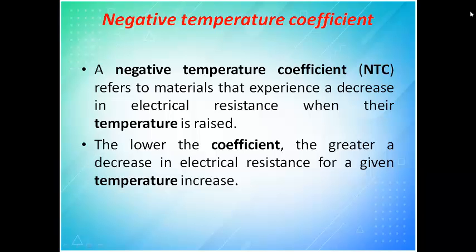And if this temperature is rising, again the resistance will fall. So this becomes a chain reaction. Due to one thing, another thing is happening. Because of the flow of electrons itself, the temperature rises, and if the temperature rises, again resistance will fall. So this leads to the entire burn of your semiconductor devices.